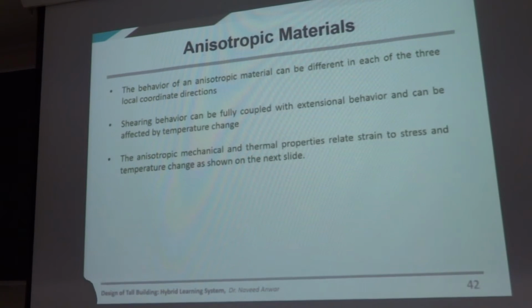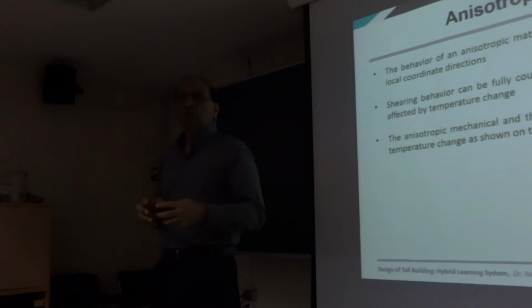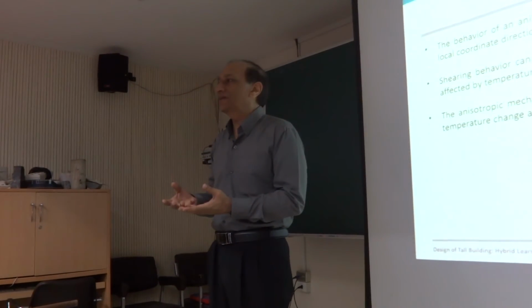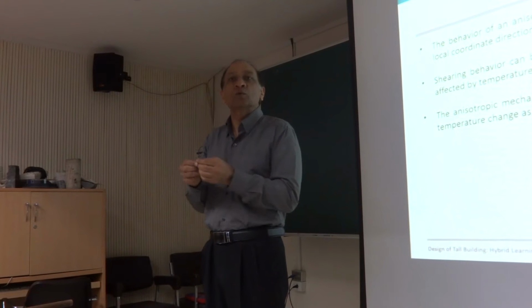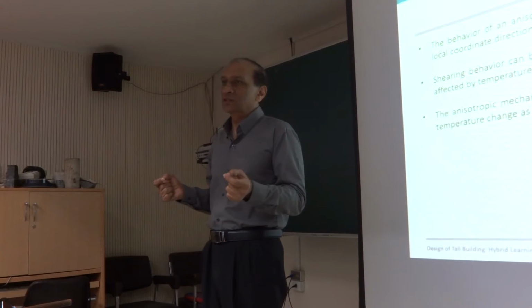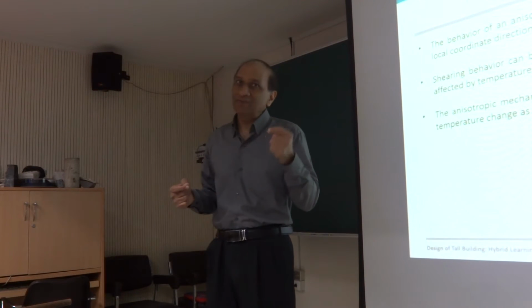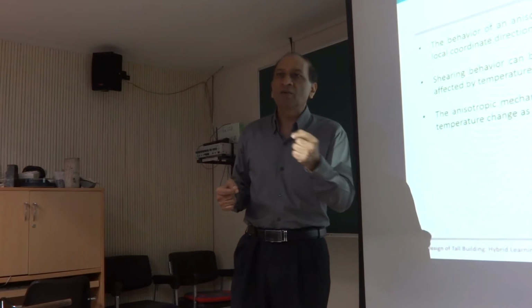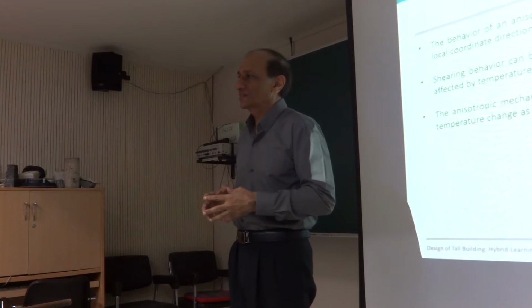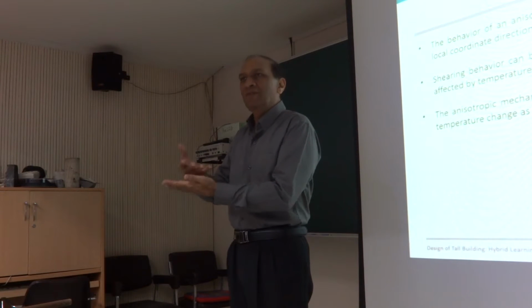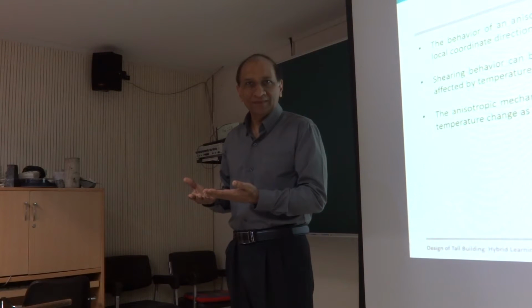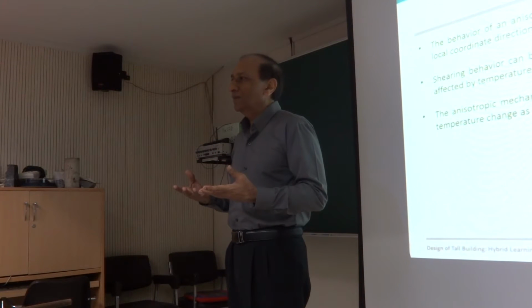Let's say we take a beam. Normally we model the beam as a line element. So we have no choice but to assign isotropic properties to that beam because it doesn't have the ability to model in the other two directions. So it has only one direction. So the properties of the materials, no matter which material we are using, have to be only isotropic. So it's not that materials have different properties, it is our modeling of those properties that makes a difference. Same concrete, when we put in a slab, becomes orthotropic. Same concrete, when I put in a dam, becomes anisotropic.